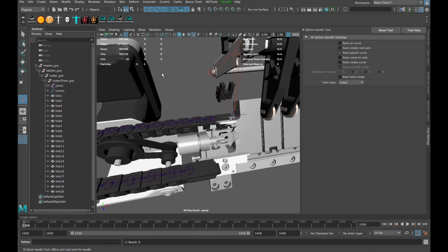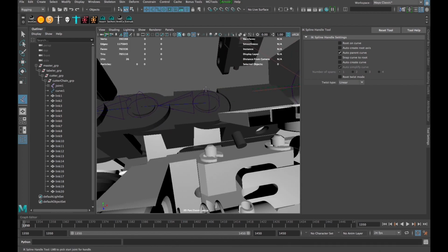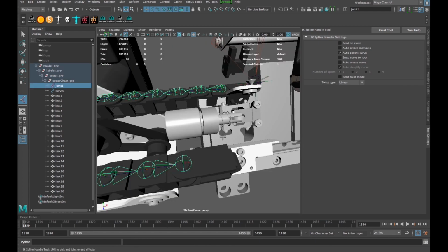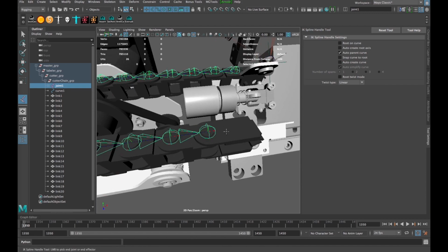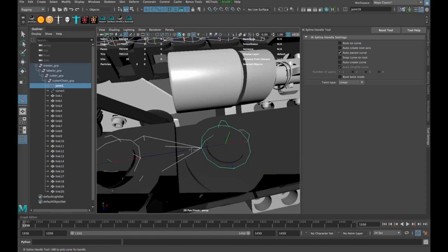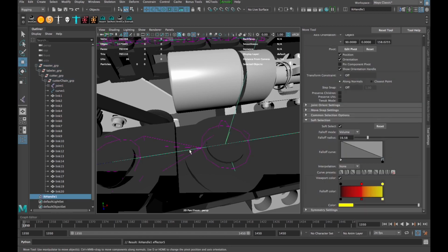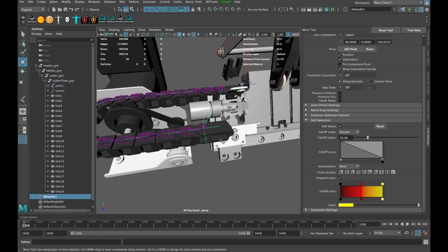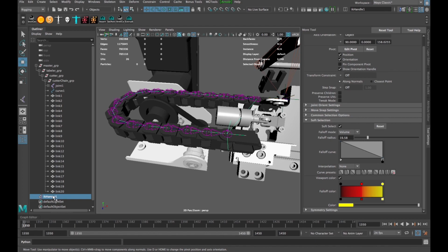In the bottom left-hand part of the screen you'll see a tooltip for left mouse button to pick Start Joint. So I'm going to click the first joint, self-explanatory, the Start Joint, and then the next instruction is pick End Joint. So I will pick the last joint. The third instruction is to pick the curve to drive the IK spline. Pick our curve, and it creates this IK handle. I will middle mouse click and drag this IK handle into our group along with everything else.